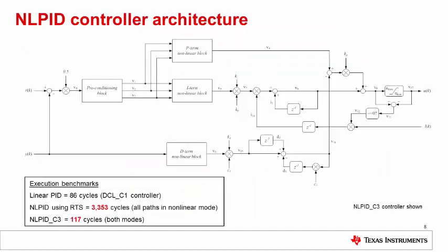Here we see the structure of the nonlinear PID. The detailed structure in the right half of the diagram is nothing more than a series-form linear PID controller, similar to the PID_C1. The nonlinear blocks on the left are where nonlinear action takes place.